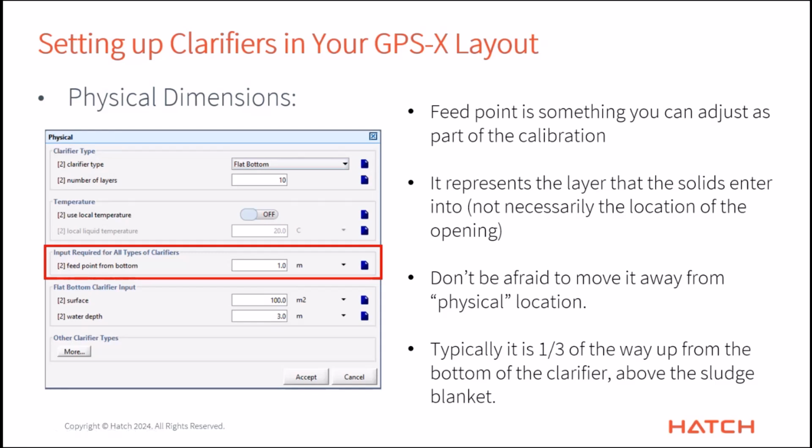This is also typical if you have some sort of baffling or other things going on in your clarifier that we don't really have explicitly represented in the model. You can adjust and account for those things by adjusting your feed point.